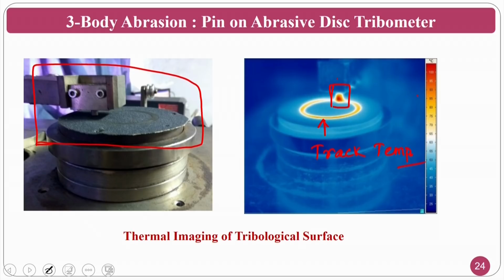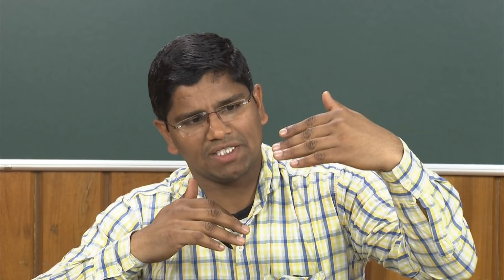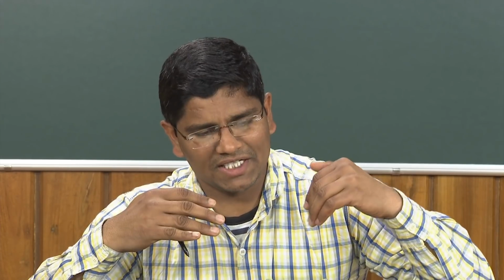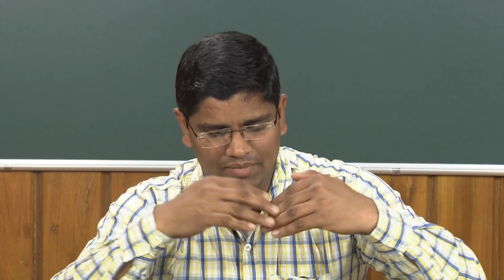Because we were talking about frictional heating, this is completely because of frictional heating. The temperature is rising to around 70 to 80 degrees, so it is a huge amount of temperature. Not in the machining operation, where severe plastic deformation gives you the major temperature, and apart from it, frictional heating is also there. So severe plastic deformation gives the major amount, and frictional heating also gives some part. Because of this, the temperature goes up.